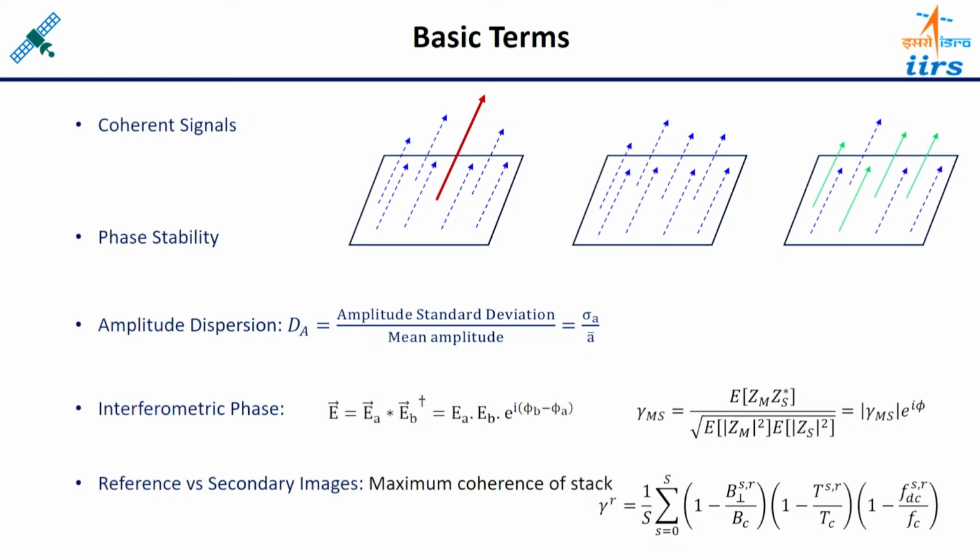Out of these 3 you will choose the situation in which the maximum coherence is there. Suppose in the case where the third image is the reference, the total coherence is the highest among all 3. Then the third image can be considered as the reference image. The first and second you cannot consider, because the sum of coherence for their combinations is not maximum.